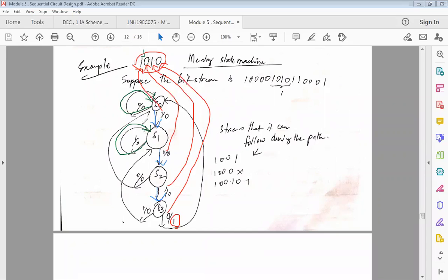So what I will do is I will not disturb state S0. S0 is set now. I will be in the same state because I've already received 1. So I will look for the next state, which is 0. Till I get to 0, I will be in the same state, because 1 is already received. 25% of my work is done, right? So I don't have to go back again and start from 0. Understanding, students?